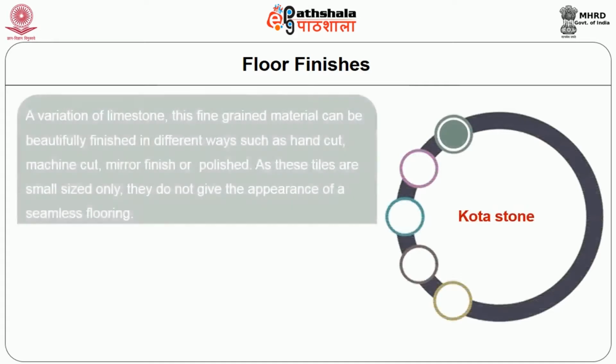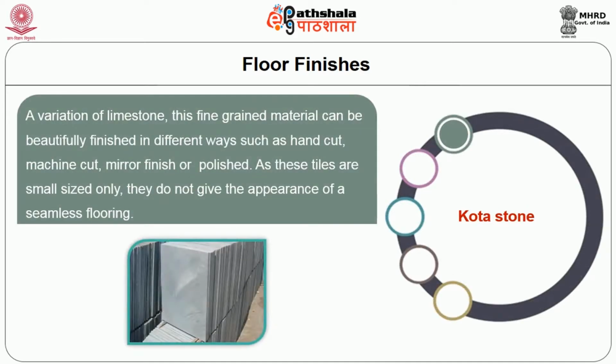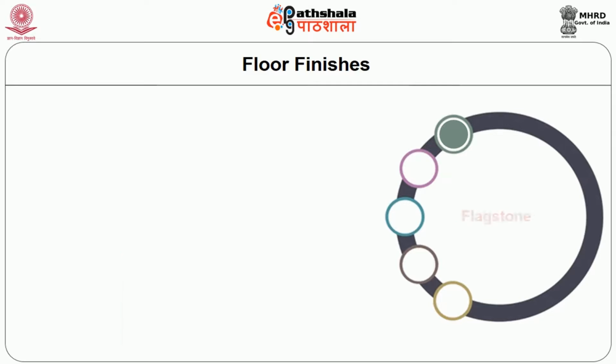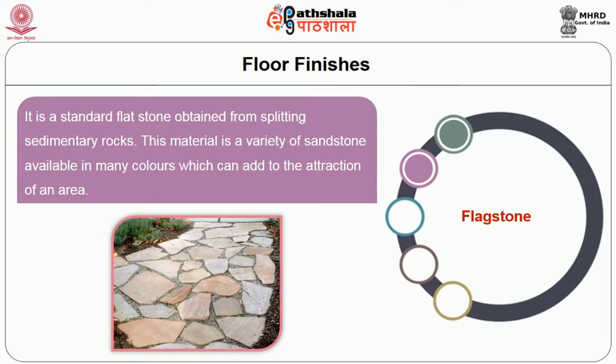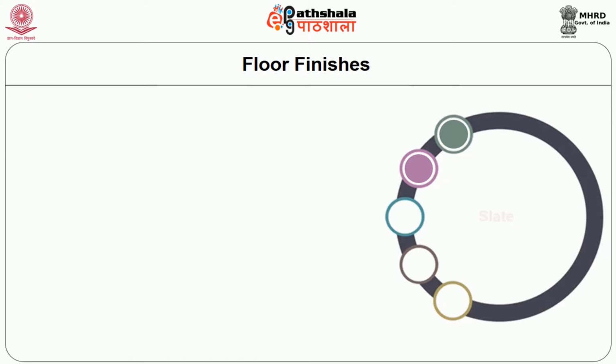Kota stone, a variation of limestone. This fine-grained material can be beautifully finished in different ways such as hand cut, machine cut, mirror finish or polished. As the tiles are small sized only, they do not give the appearance of a seamless flooring. Flagstone is a standard flat stone obtained from splitting sedimentary rocks. It is a variety of sandstone available in many colors which can add to the attraction of an area.